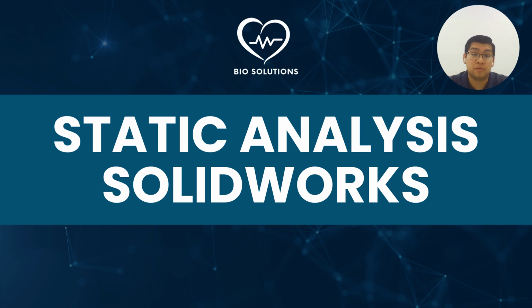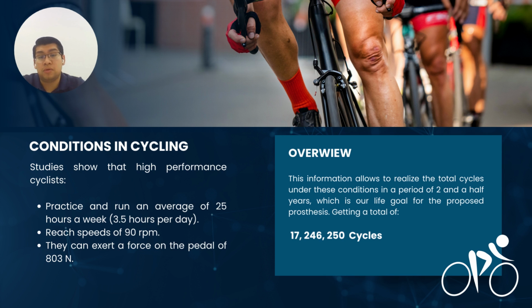In this case, we implemented the tools that SolidWorks gives us. For our analysis, we took into consideration the following aspects. Studies show that cyclists practice an average of 25 hours a week. They reach a speed of 90 revolutions per minute and they exert an average force of 803 newtons on the pedal. With this information, we can estimate a total of 7,246,250 cycles, considering that our prosthesis has a 2.5 year life.